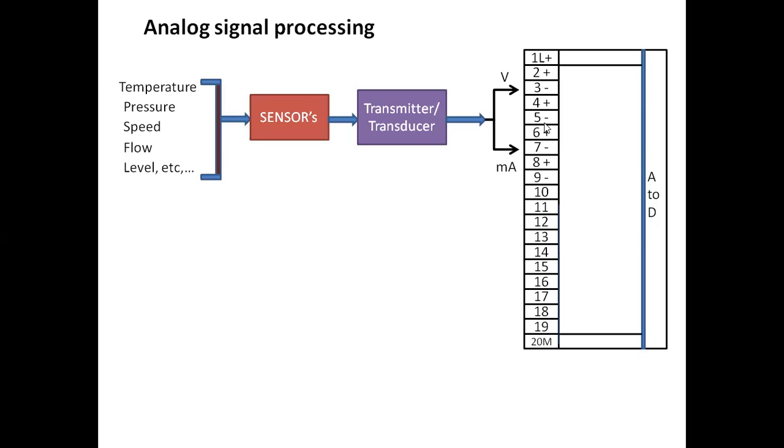These are further connected to your analog input module at some particular terminals. We have to check the wiring diagrams of your analog module to see where we have to provide supply and where we have to give the signal. Your voltage or current signal will have two wires, right? Those two wires, plus and minus, we have to connect on your channels, known as channel 0, 1, 2, 3 like this. A maximum of 8 inputs will be available on your module, so channel 0 to channel 7. The minimum is 2 inputs on your modules.